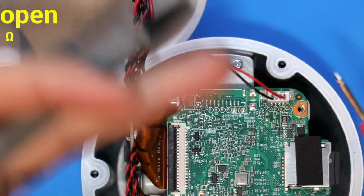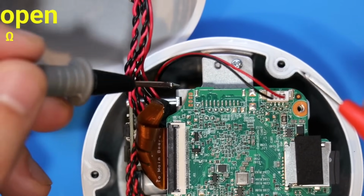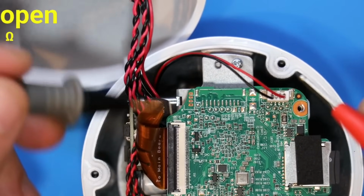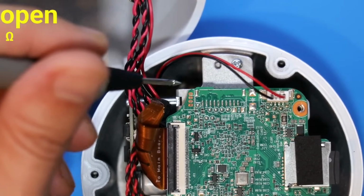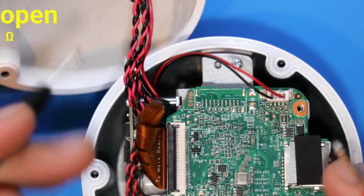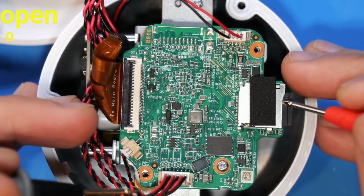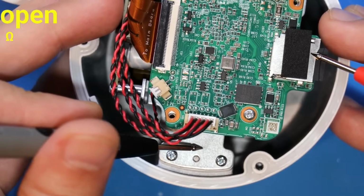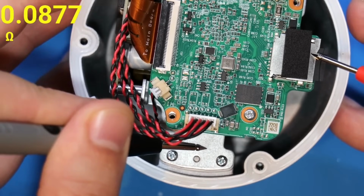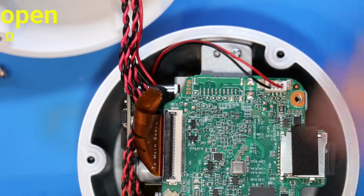Currently I don't have the device powered on. The first thing I want to do with our four candidate pins here is figure out which one is ground. Now, when I'm actually interfacing with that UART interface, I'm not going to connect to the ground pin there. For practical reasons, I could, but there are just so many other areas. Shielded components are oftentimes grounded, so the top of this SD card adapter, and then I've got this metal housing down here. We can see from the beep and our on-screen overlay that those are both grounded.